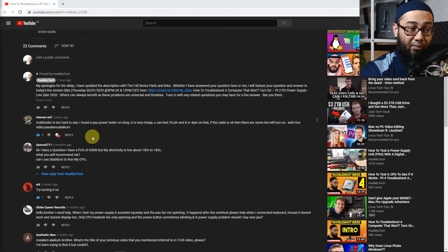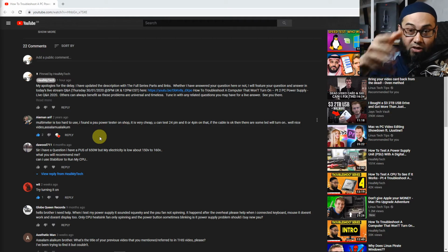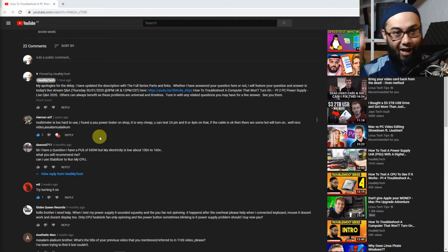Okay, sure, I mentioned in the video you can get yourself a PSU tester. Like he mentioned, you can test 24 pin, 8 pin and 4 pin, and hopefully it works fine. I know that in some companies, if they have a lot of power supplies to test, this will be a first base test they would do, but it will not be an ultimate, conclusive test, because it has limitations.